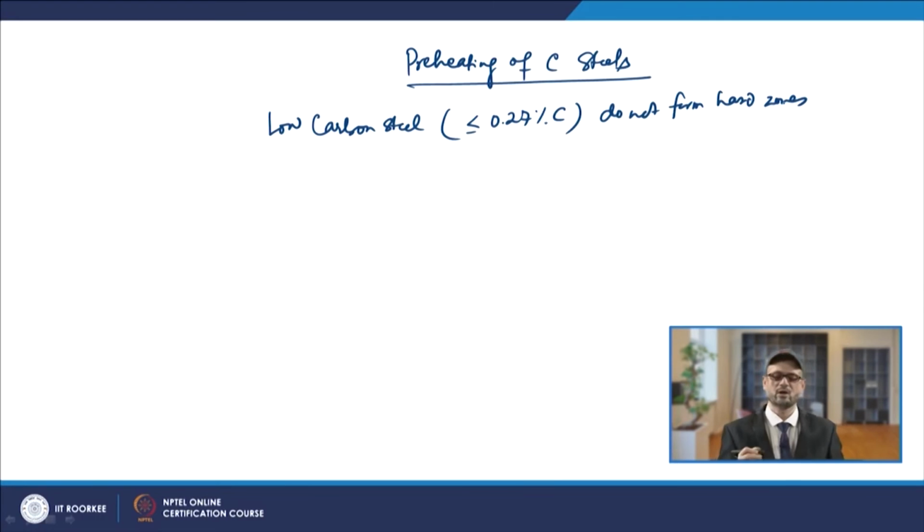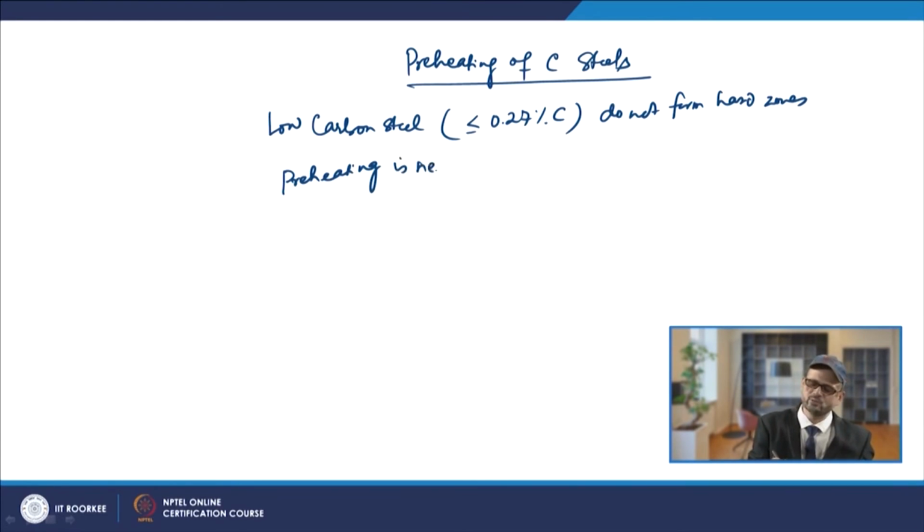So, when you have these low carbon steels, preheating is necessary only when welding exceptionally heavy sections.